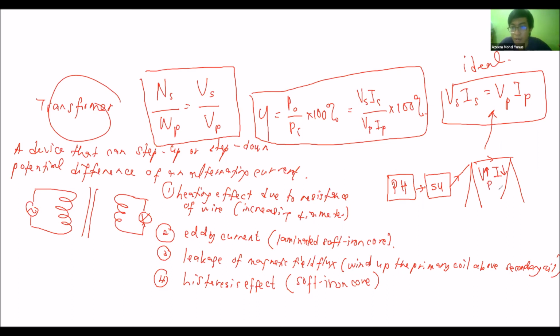So with resistance constant, the power loss reduces. The power loss here is I squared R. The resistance is the same because we don't change the wire. We can change only the current. Reduce the current, and the power loss overall will be reduced. We reduce the current by increasing the voltage, the potential difference. How are we going to do that? We use a step up transformer.